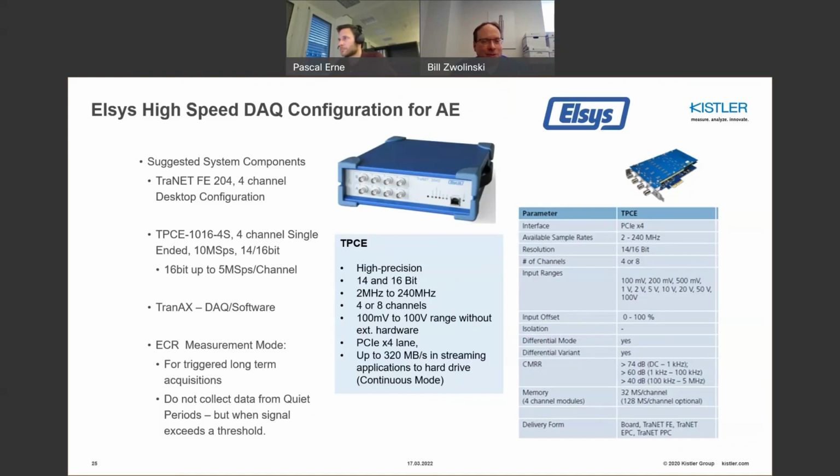Nowadays, the sensor is usually the weak link to the data acquisition, because data acquisition systems can have dynamic ranges of over 100 dB. And any sensor, I don't care what type of measurand, that has 100 dB dynamic range is really a special sensor. So keep in mind that nowadays there's such a wide choice of data acquisition. And it's always good to find your favorite application engineer when you're trying to figure out what to use, because the devil's in the detail when it comes to data acquisition.